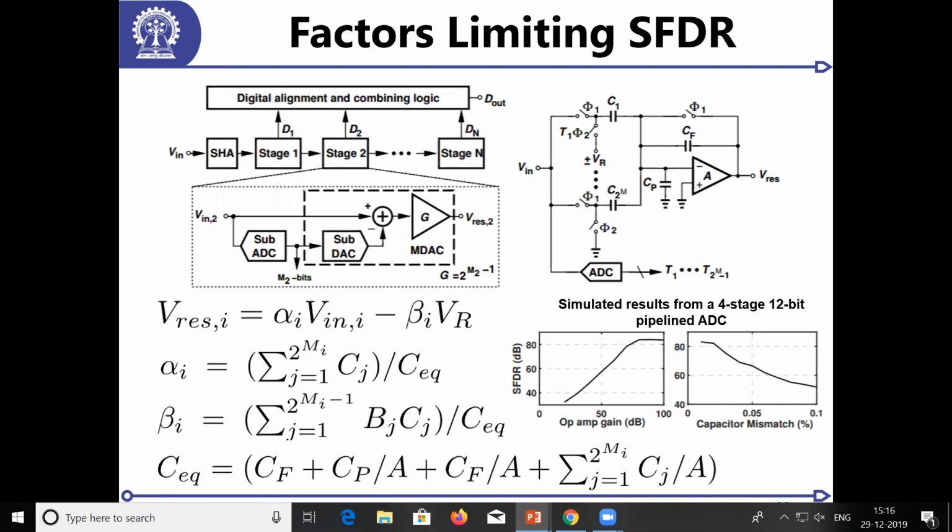So the steps will be perfectly this, and these steps will be equal. They might not be exactly 0.1, but they will cancel out each other. So the average of this will always be 0. As long as I have this average equal to 0, it should be non-subtractive. And in a differential implementation, it always comes out to be 0. Every clock cycle you do it. So you trade off accuracy, speed versus the accuracy.